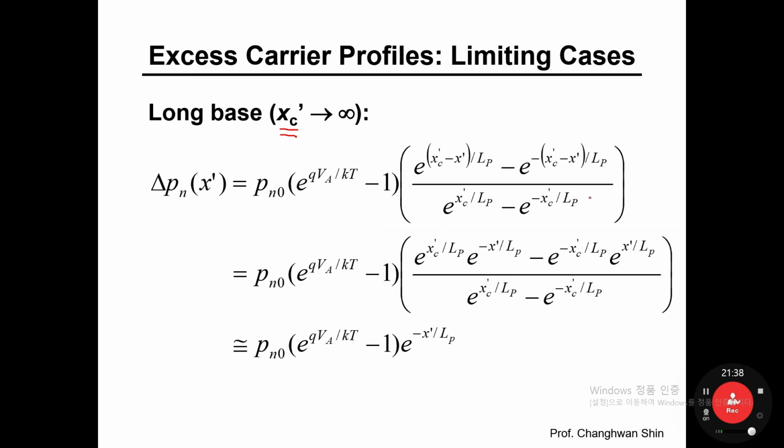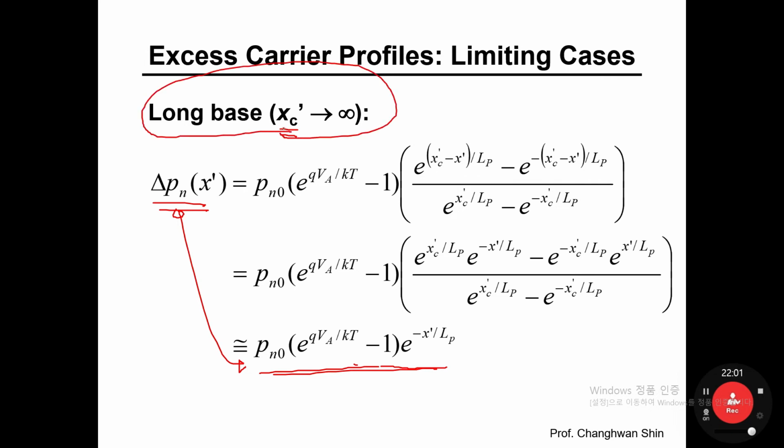We're gonna get the same equation for delta p sub n as in the ideal diode analysis, same here. Take a look at the conclusion. Yes, that's the equation that we obtained in the ideal diode analysis. So to confirm mathematically, this assumption would still be well valid.